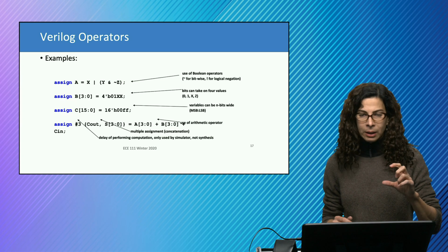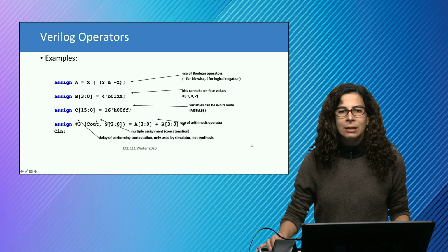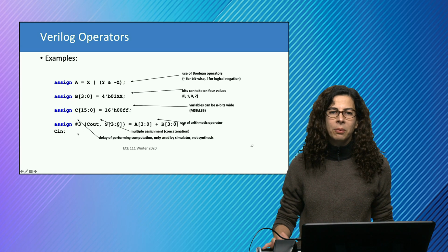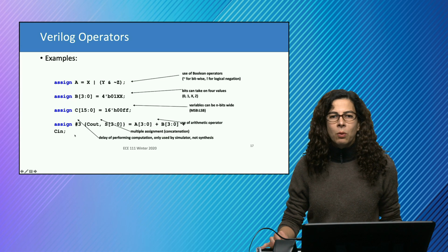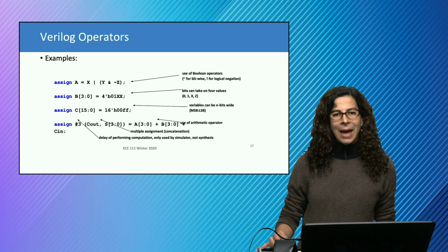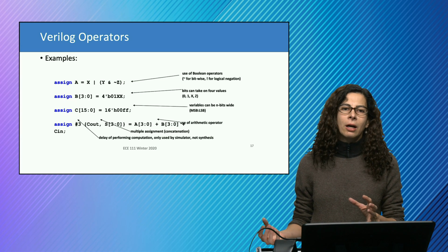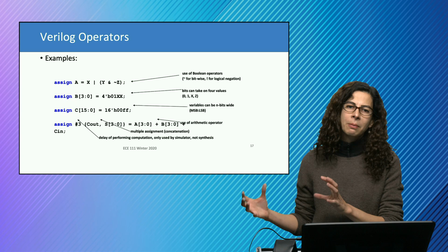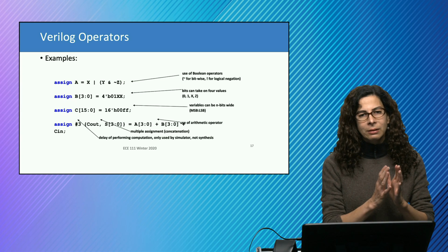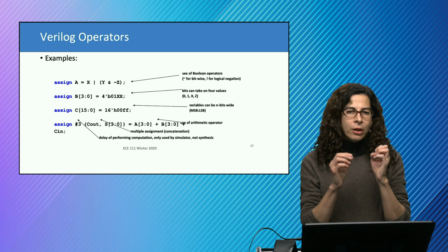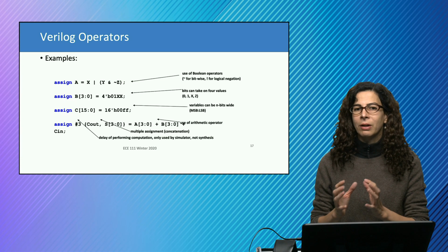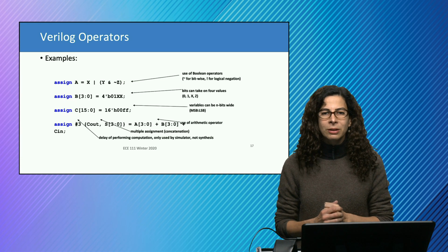There is one more construct that is pretty useful in simulation, and we will see that on and on in the class, and that is a hash number, which you could put right after an assign. What this one does is it basically executes or assigns outputs from a combination of the inputs. Output is computed, for example, in simulation, but then it shows 3 clock signals later. And this doesn't have a unit. The unit is basically the unit of a clock signal.